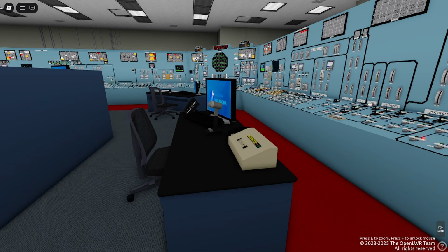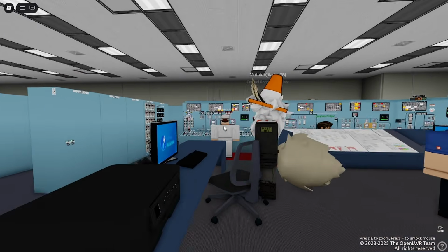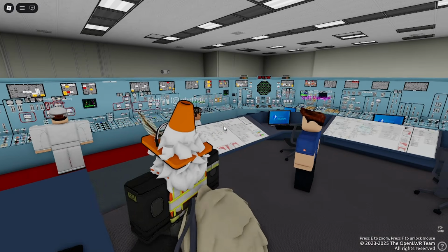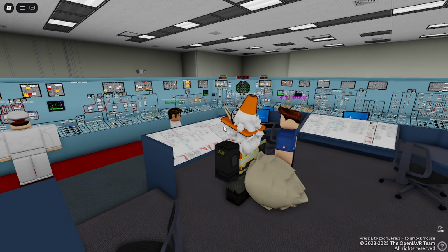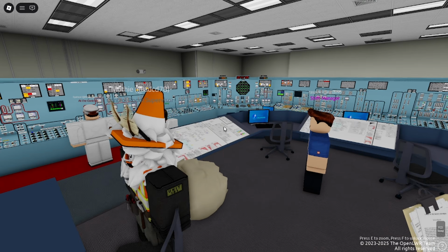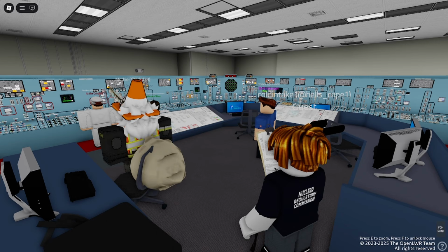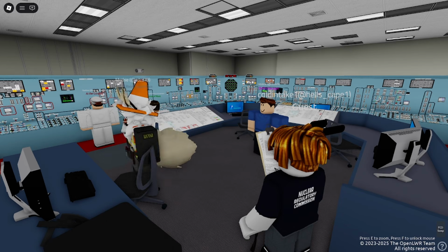Super. Yes. Could you adjust the PID for output to SGT so that the drywell pressure is kept at 0.6? Adjust the outflow valve to standby gas treatment so that drywell pressure does not go below 0.6 pounds. That's correct. CRS, yes. The outflow valve to SGT is already fully closed. That's correct.